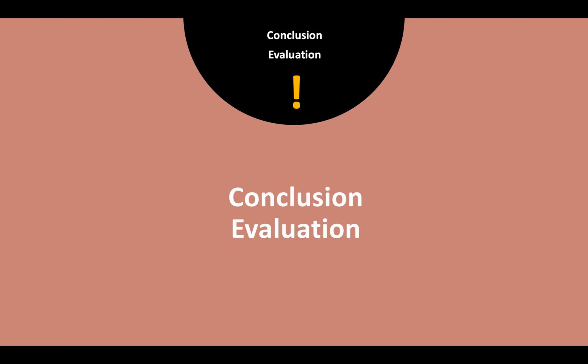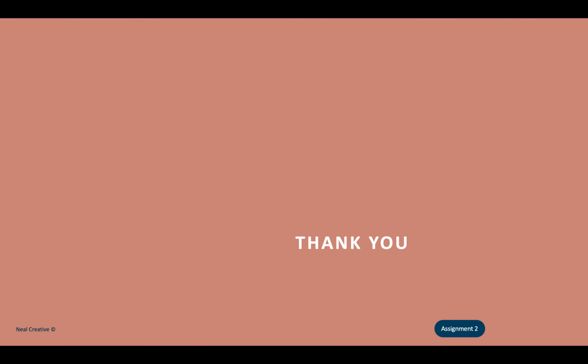So in this assignment, I have shown how to use Prosper and how to calculate the IPR and the VLP curve with different pressure and skin factor. As can be seen from the previous slide, when the skin factor increases, the flow rate declines slightly. Furthermore, I have already designed a simple well by using the gas lift method, and also shown the pressure will be increased when the temperature also goes up, when the depth tends to be higher. All in all, Prosper is a useful software for engineers to solve some problems in this major and support engineers. Thank you for listening.